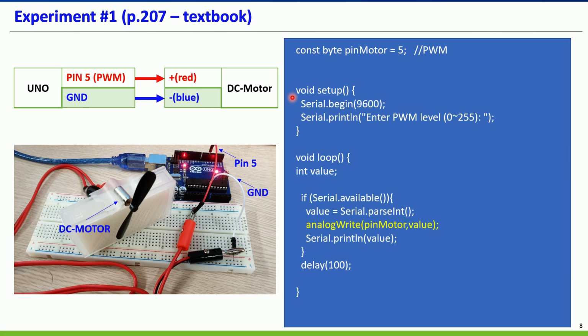In this case, we just drive the DC motor directly from pin 5. This one is actually not recommended for driving a DC motor, but anyway, it is good for basic driving using pulse width modulation, because your DC motor has a small voltage input. I mean the voltage power rating is very small. And I think this is just okay.